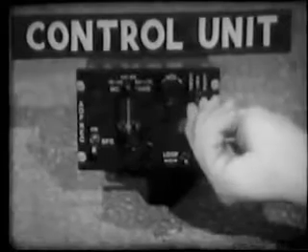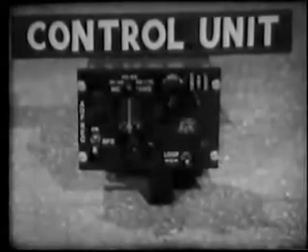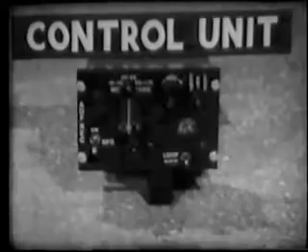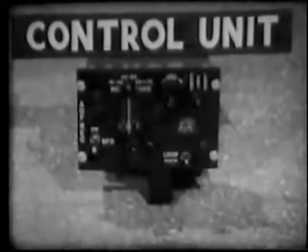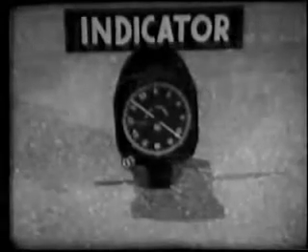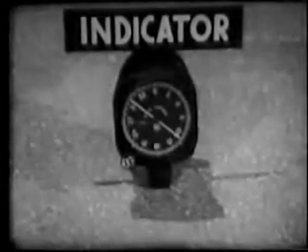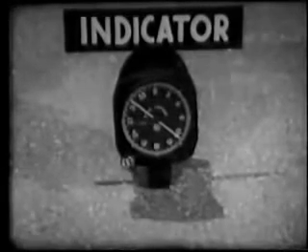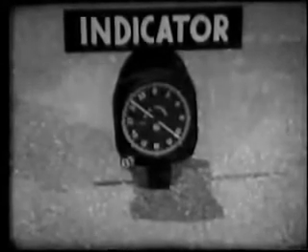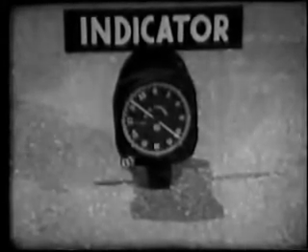In the compass position, we have the automatic direction finder. In this position, the combined signals of both the directional and the non-directional antennas are fed to the receiver, and the indicator will point to the station at all times automatically. It is in this position that we will normally operate the ADF for radio navigation.